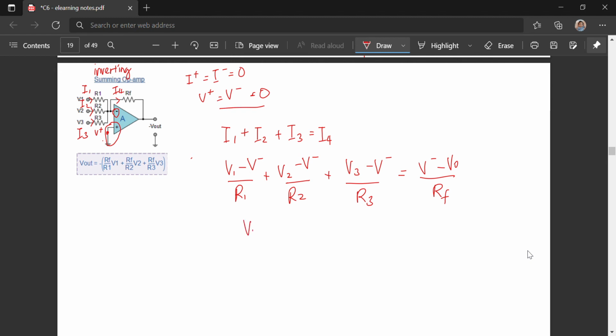So you have V1 over R1 plus V2 over R2 plus V3 over R3 equals minus V out over Rf.